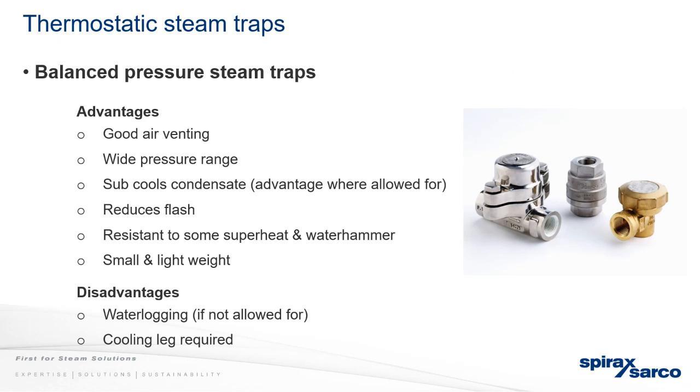Reduces flash because it's subcooled, so there's less temperature range difference between the atmospheric or whatever pressure is down the pipe and the steam or the condensate you've just had. It's resistant to some superheat and water hammer. So it's resistant, yes, but it still has the ability to be affected by both.